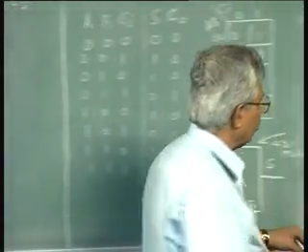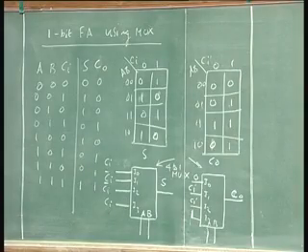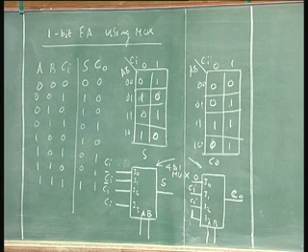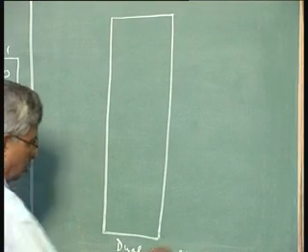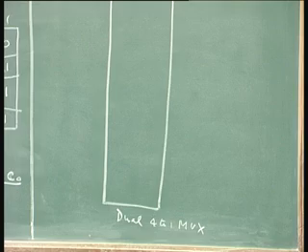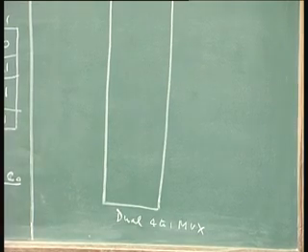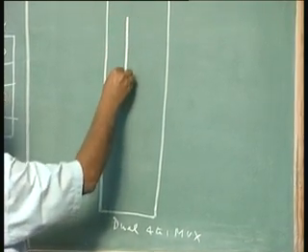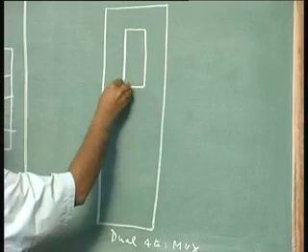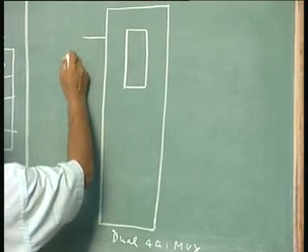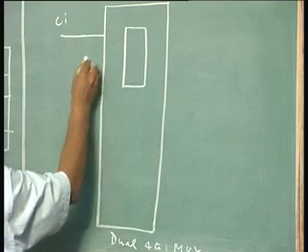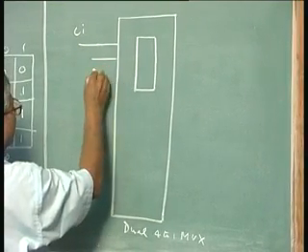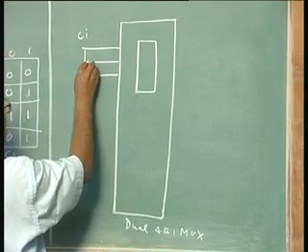So, I will have this full adder which is going to look like this. It is called a dual mux, dual 4 to 1 mux. Dual means 2 of them in 1. Dual mux, the first mux, I will connect Ci, second and third I will connect Ci bar.